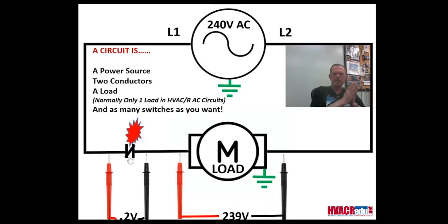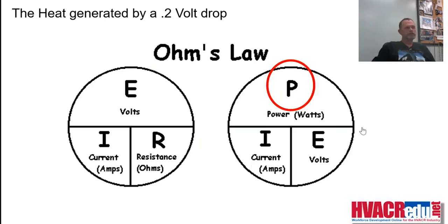How many of you guys have found contacts welded together? It's not an everyday event, but when you find them, it's sort of ugly because something burned up pretty good if that contact welded together. Okay? Just saying. Heat generated by a 0.2 volt drop.